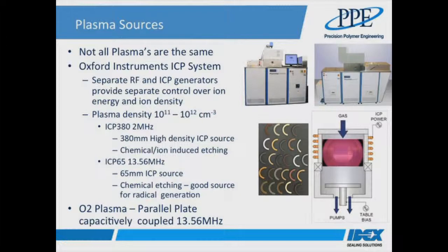As I just mentioned, etching tends towards the use of high-density plasma sources, but we also need to take into account the common use of remote plasma sources used to clean deposition chambers. Such remote plasma sources are again high-density, inductively generated plasma designed to create active species that will react with materials coated around the vacuum chambers to which they're connected. So what we've tried to do is find equipment, or more precisely partners, that can simulate the various different sources and then also supply the chemical environments that are commonly used.